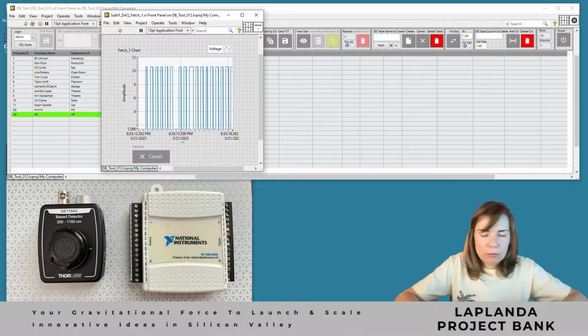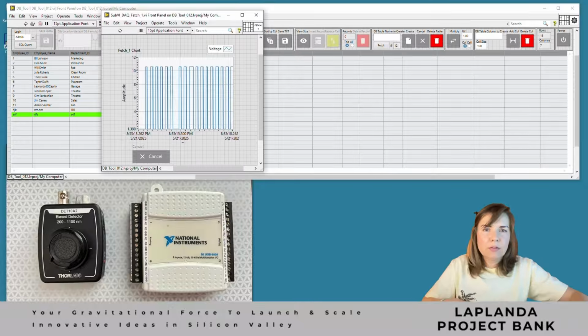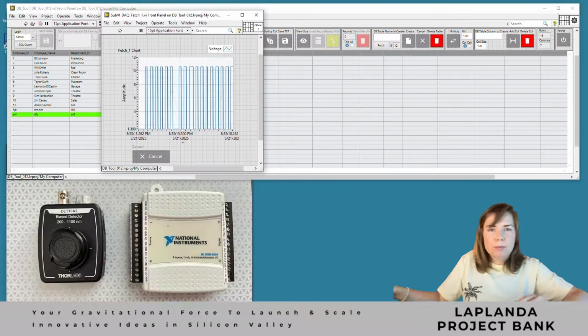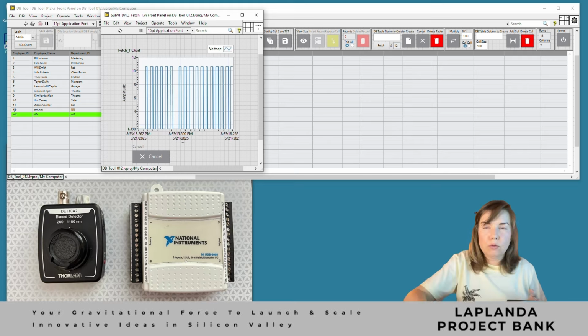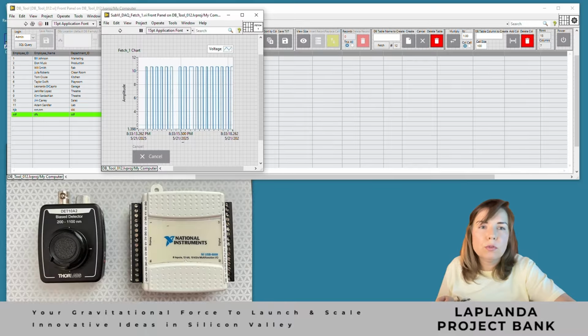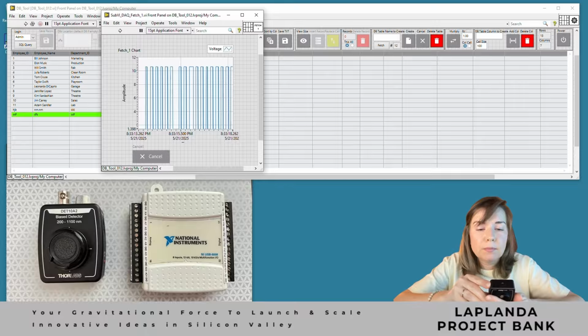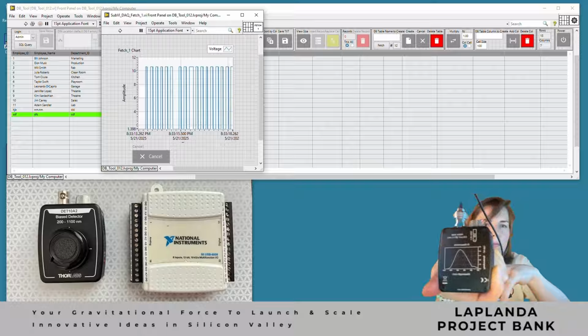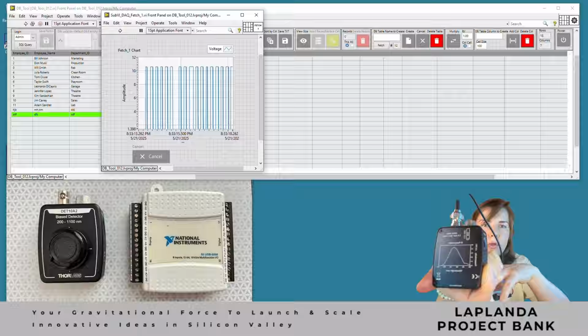There we go. Well, let's also check whether everything really works. Here I have a flashlight on my phone. Let's test whether our photosensor actually reacts to light. Before that, let's make sure in what wavelength range our photodetector operates. On the back side of my photosensor, we can see the bandwidth range from 400 nanometers to 1000 nanometers. We know that in this electromagnetic spectrum we have visible light. And here the peak is indicated around 700 nanometers.